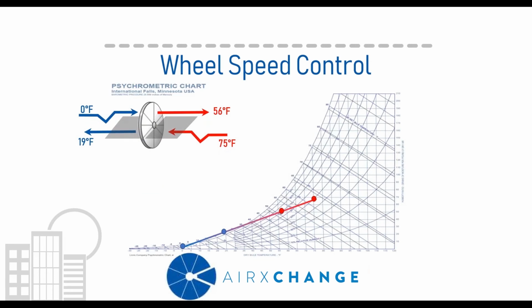Plot this on the chart. So as the wheel starts to slow down, the leaving conditions gradually get closer to the entering conditions. The exhaust air is going to get a bit warmer, and the supply air is going to get a bit cooler. So slowing the wheel down has moved these two state points away from the saturation curve.